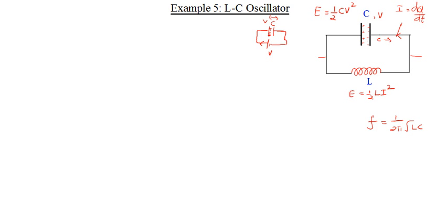So you can see that during an LC oscillation, what is oscillating is the charge. Some charge Q is oscillating between the capacitor and the inductor, or I can say it is oscillating between the positive and negative plates of the capacitor, with the energy becoming magnetic energy and again converted into electrostatic energy, back and forth. So that sets in what is known as an electrical oscillation.